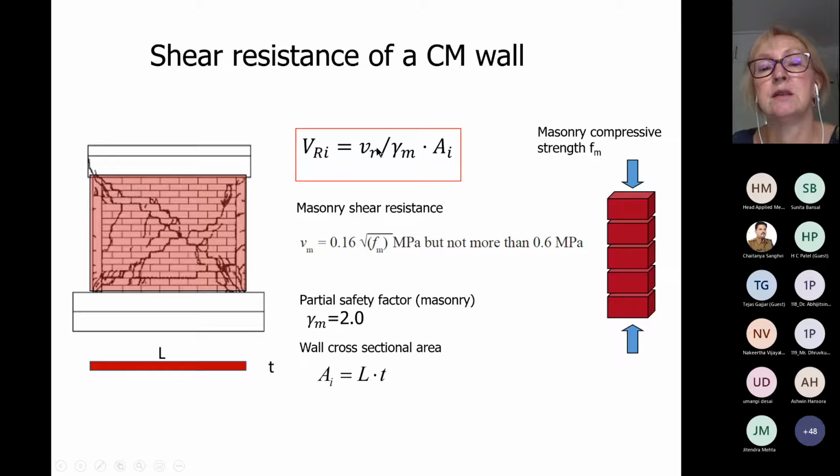The maximum stress that this masonry wall can take is the basic shear strength. So that is that VR. You remember we were talking about VM. Actually, that should be VM instead of VR. In this case VR could be due to masonry, or due to steel if there is steel. So in this equation we should have VM and not VR, maybe you can correct that, because of the nature of unreinforced masonry.